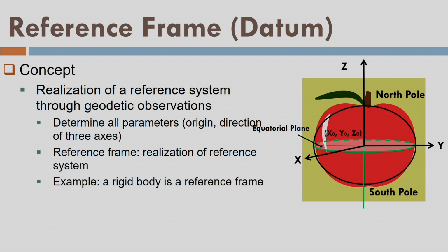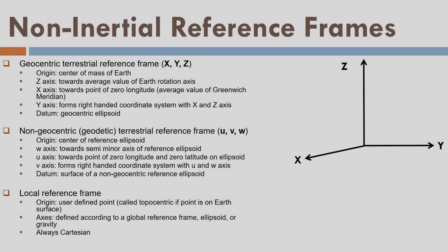And remember that if I fit the geocentric system, that means the origin is at the geocenter of the earth and the rotation axis is completely aligned with this, I can understand that it can be a global system. That is the rotation axis, and that is the semi-major axis A and semi-minor axis B. We have already defined it.